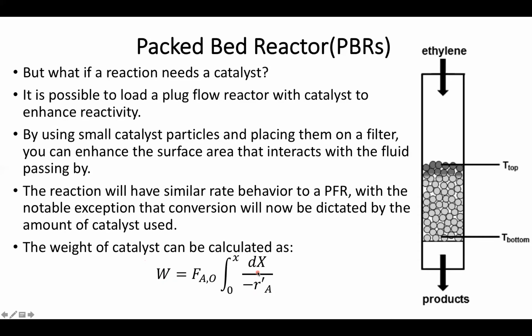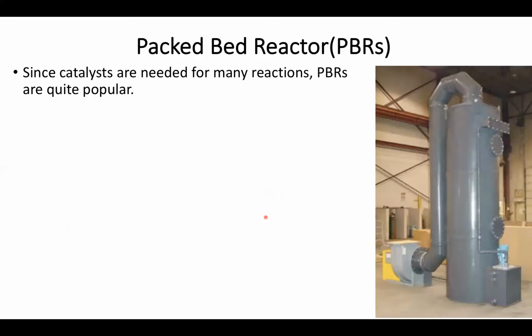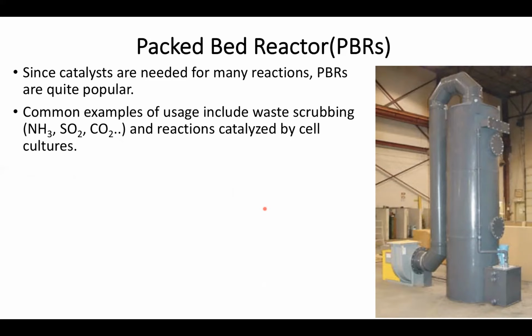And again, it will still show a position dependence, where position is related to time through this flow rate. So it's worth noting that these packed bed reactors bring in the best parts of a plug flow reactor with a catalytic system. So packed bed reactors tend to be very popular.